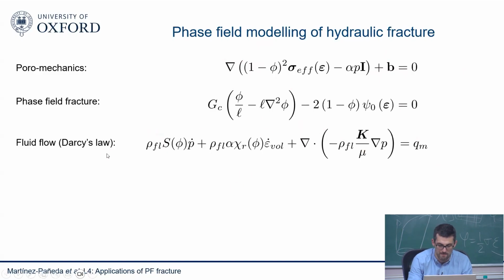So the fluid flow. How we do that in practice in Abaqus with a UMAT, now we need a UMATHT. I will discuss that at a later date. There's a date that we talk about all implementation. For the time being, the key point is that phase field is very convenient to use with multiphysics problems. So you can easily combine these equations. And then the only thing is that, of course, these equations that you have in Darcy's law, some of the parameters will have different values inside of cracks and outside of cracks. So you need to come up with a way of interpolating those values.